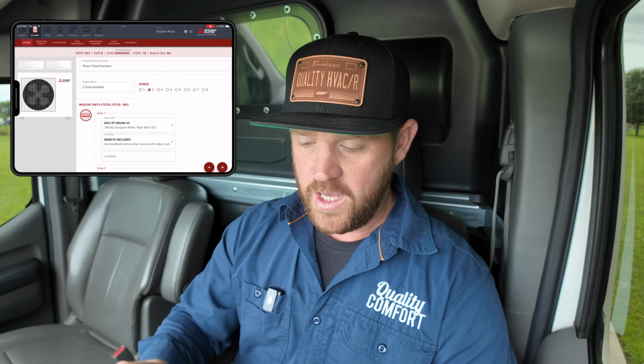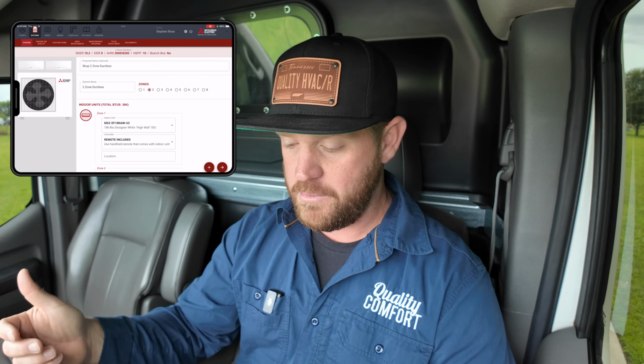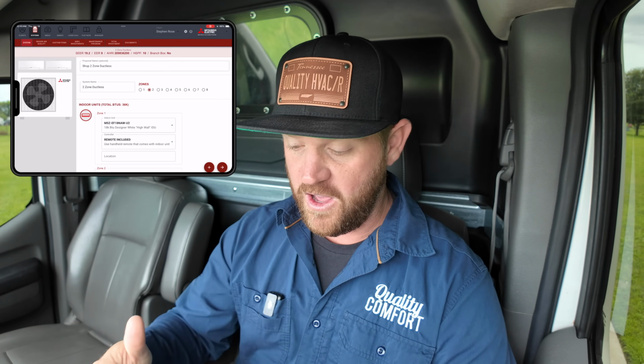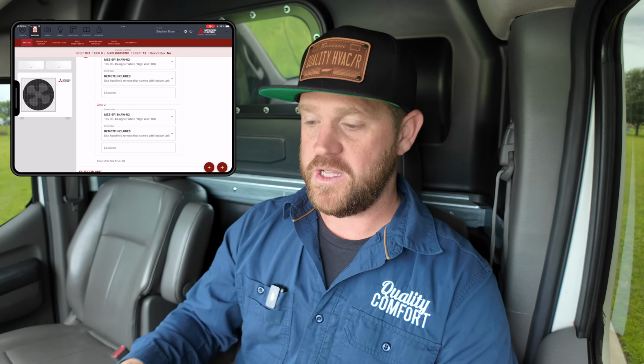There's no guesswork, trying to figure out, hey, is this an AHRI matchup? It tells you right here at the top, and it even gives you the number of the AHRI. It tells you the SEER rating, the EER number, the HSPF, if it needs a branch box. It really makes it simple for you as a contractor, running and gunning basically. Like if you're just out here doing estimates, it just saves you a ton of time.